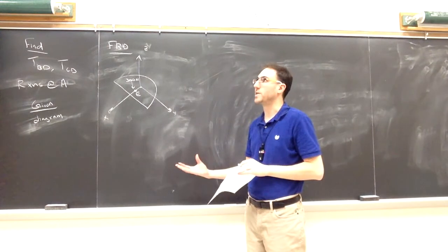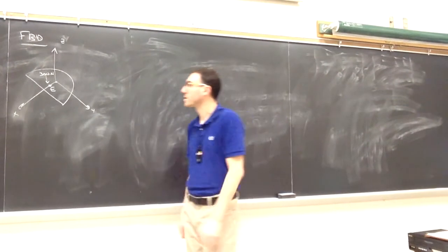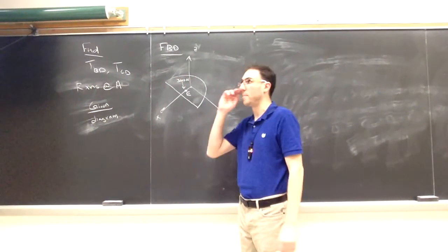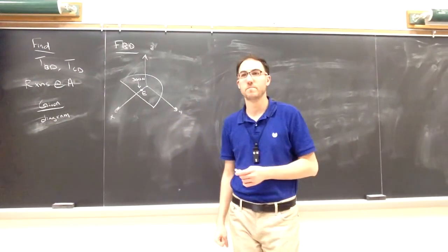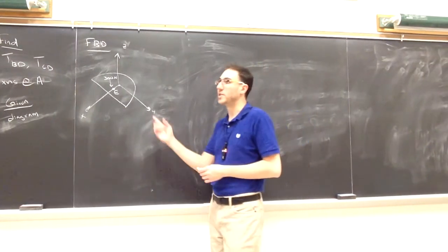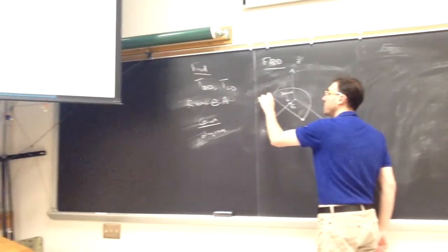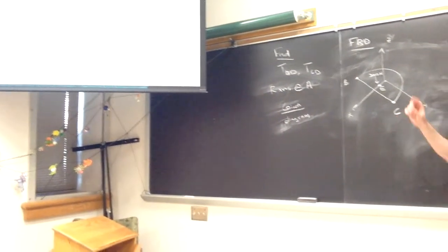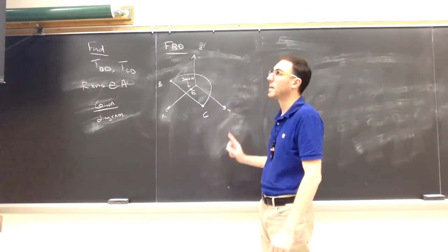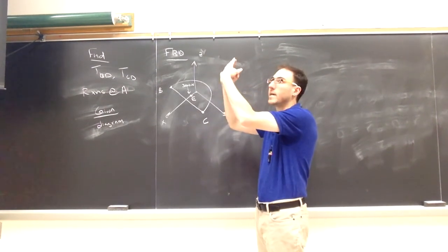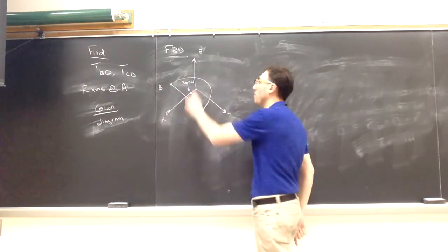Right, that's the only applied force here, so now we need to include things that come from supports and connections that we've disconnected it from. So what other forces, other couples are going to be acting on the blue platform now that we've disconnected it? Right, the tensions from the two ropes that we disconnected at C and at B. We know that the tension in the rope will act along the length of the rope. Now these are two different ropes, so they potentially could have two different tensions because they each individually go and meet at D, but are tied together separately. D is not a pulley, which would mean it's one continuous rope.